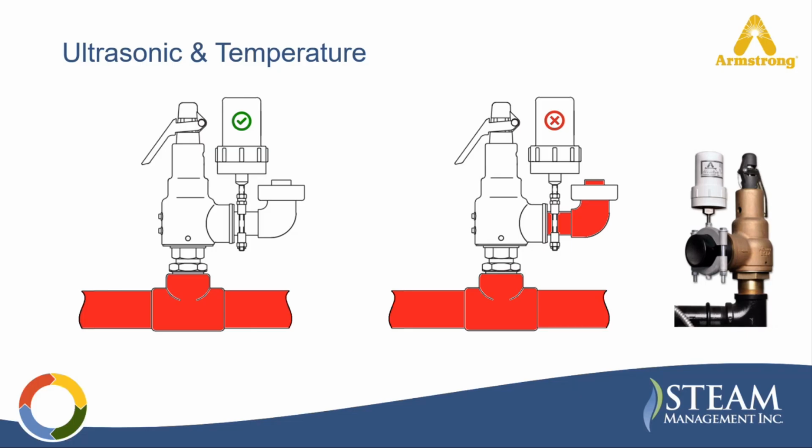By continuously monitoring temperature and ultrasonic activity around these valves, SteamEye can help identify leaking valves quickly so corrective action can be taken before the problem grows. So it's not just steam traps that we're able to give you that visibility on, but also another point where energy is sometimes lost, which is that valve testing for that safety relief valve.